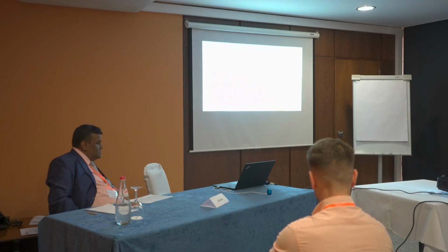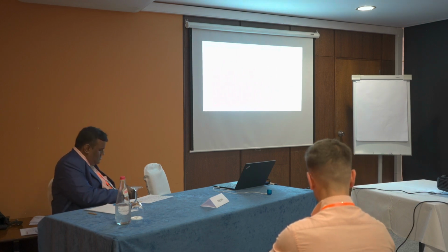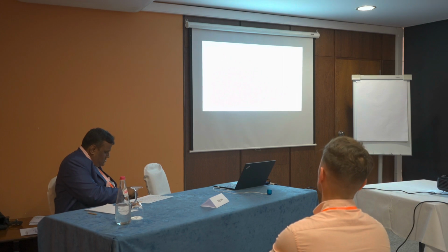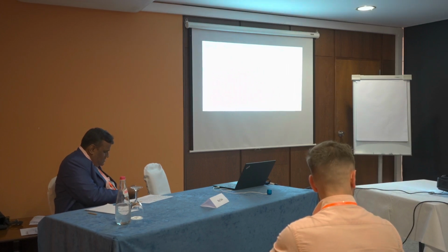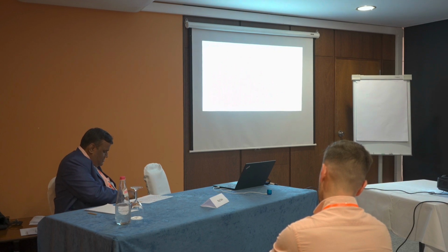In Annex 1 of ASTM E1921, which is the master curve method standard, special requirements for determining the reference temperature at elevated loading rates are described.